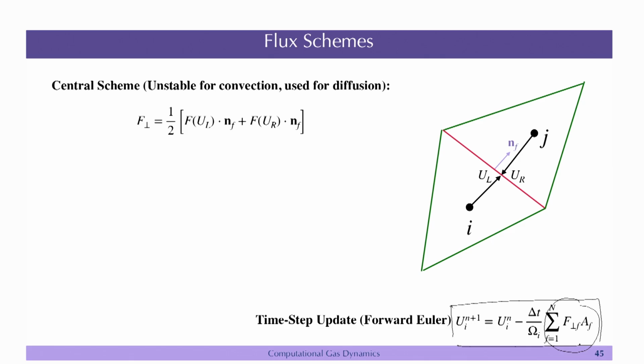This is the perpendicular flux on an interface, and you multiply with the area vector, and then you sum over all the faces. For example, this is one of the faces, you need to get the flux value here. These are our cell centers i and j, and you might have cells here also, and they will go to all the boundaries that you have.